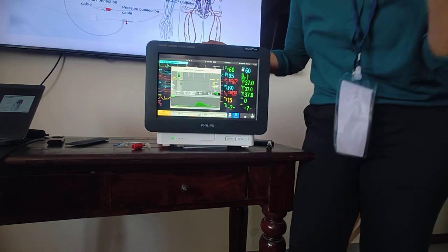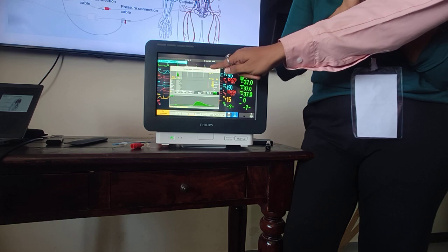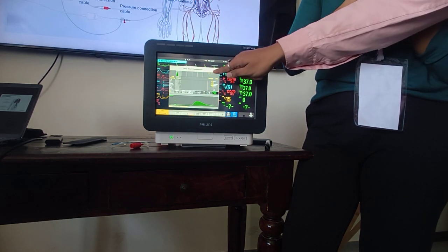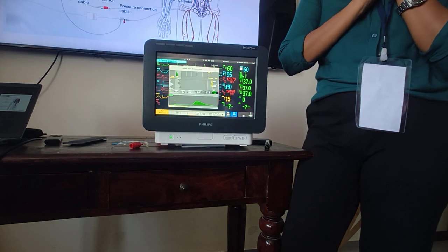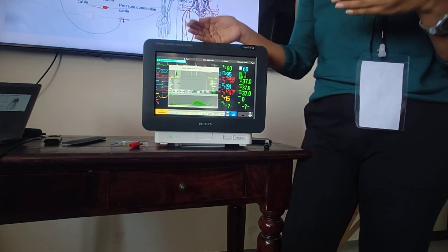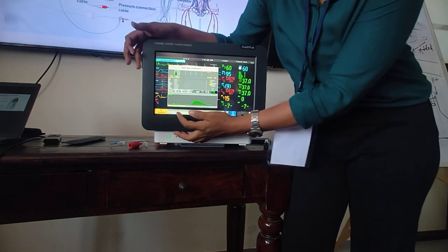But when we are doing any kind of thermodilution, have a look at the temperature difference which we have mentioned. It has to be more than 0.1, or 0.2. It will indicate immediately. If it is coming below that, that means your trial is wrong. You can delete the trial from the average. I'll show you how to do it.